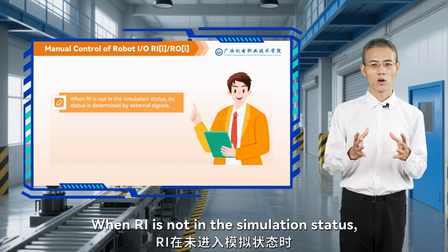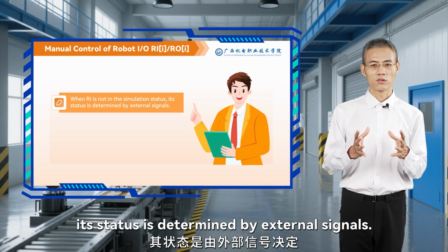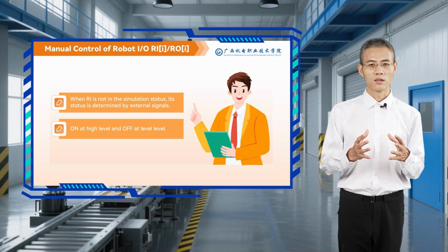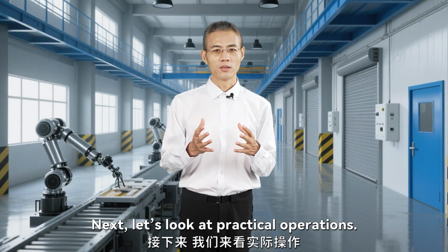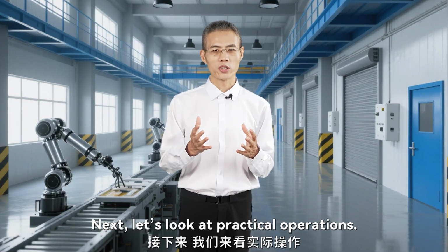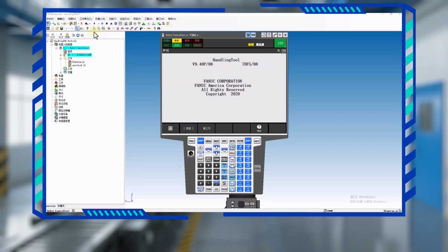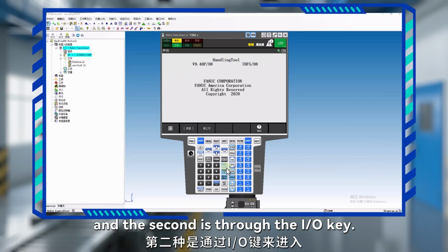When RI is not in the simulation status, its status is determined by external signals. When it's at a high level, it's on, and at a low level, it's off. Next, let's look at the practical operations. There are two ways to enter I/O. The first is through the menu key, and the second is through the I/O key.